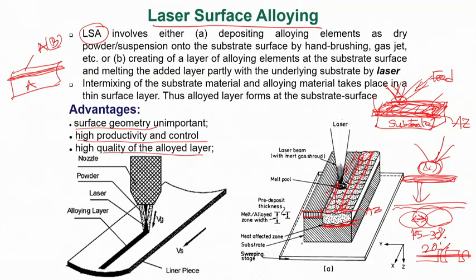Now in order to protect the powder feed or wire feed or whatever we are delivering, we also would like to ensure that there is no undue oxidation. At the delivery point, the beam temperature could be anything from several hundred degrees, like 500 to 2000 or even higher, depending on what kind of parameters we choose. Of course we can control that. The entire heat transfer is purely dependent upon the parameters we choose.